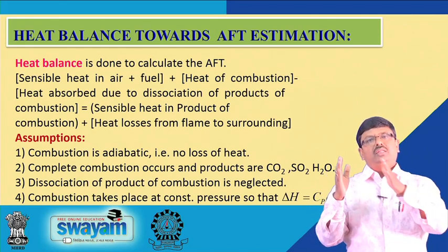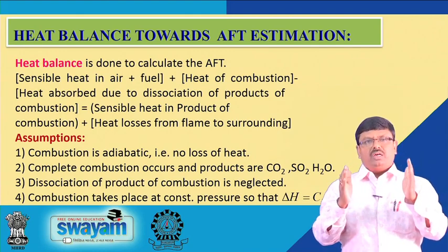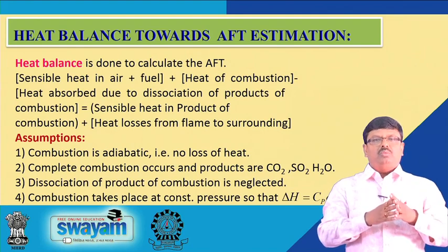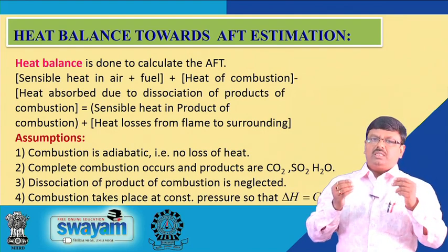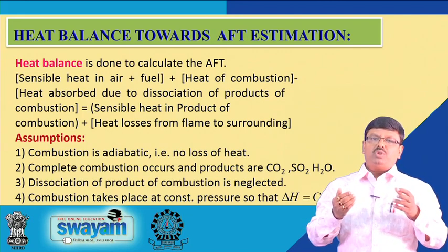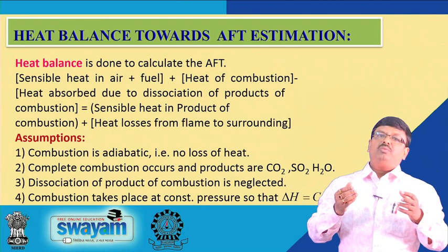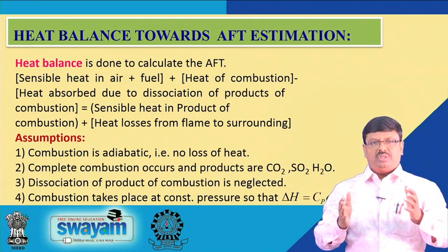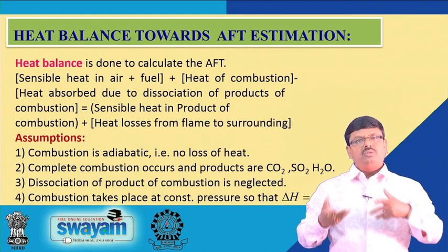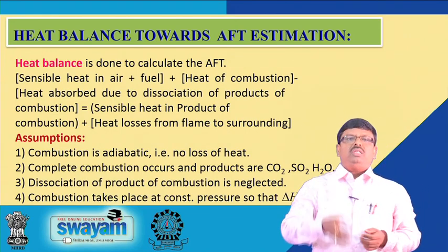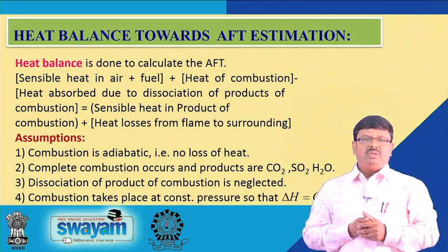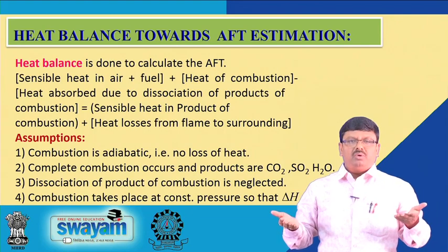This heat balance is to be done in the same fashion, considering the sensible heat and the heat losses from the system also, because in real practice it is not always possible to fabricate a 100% leak proof system. So, there might be a slim chance of heat loss, and that is also to be taken into account. These are the different assumptions that you can consider for the calculation of AFT, where the combustion is adiabatic, since it is adiabatic flame temperature.